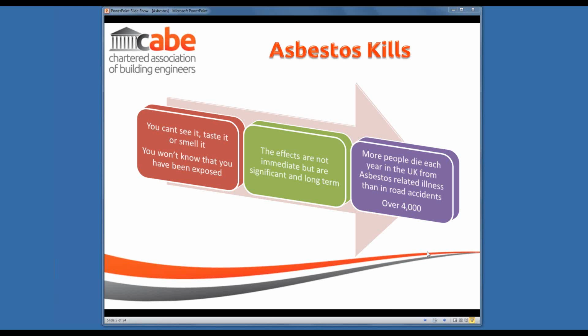One of the key issues with asbestos is it is sometimes quite difficult to identify. The way in which we refer to asbestos can be confusing. Quite often we refer to it by colour, but that does not reflect how it's going to look when you encounter it in the building. It refers to the raw mineral state of the product, and therefore you can't necessarily tell if a product is asbestos, or if you are fairly sure it is asbestos, what type of asbestos it is, simply by looking at it.